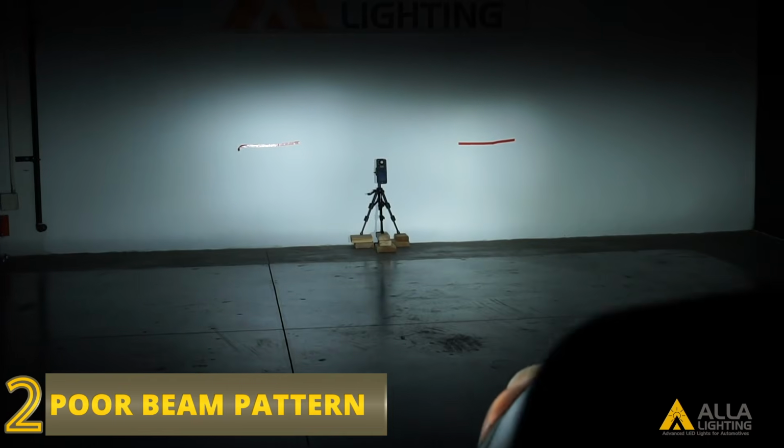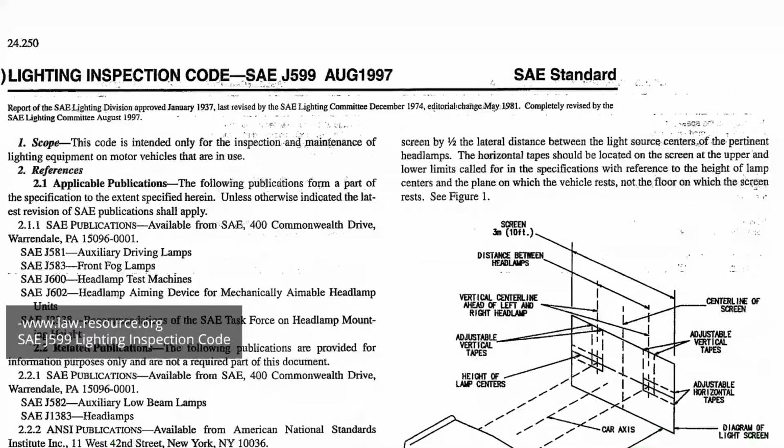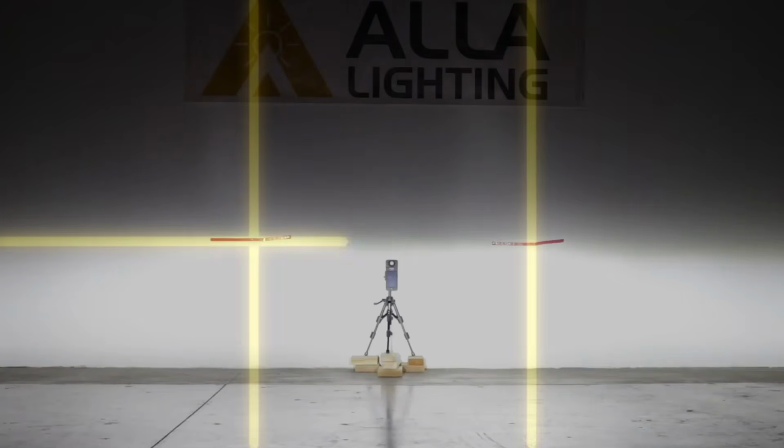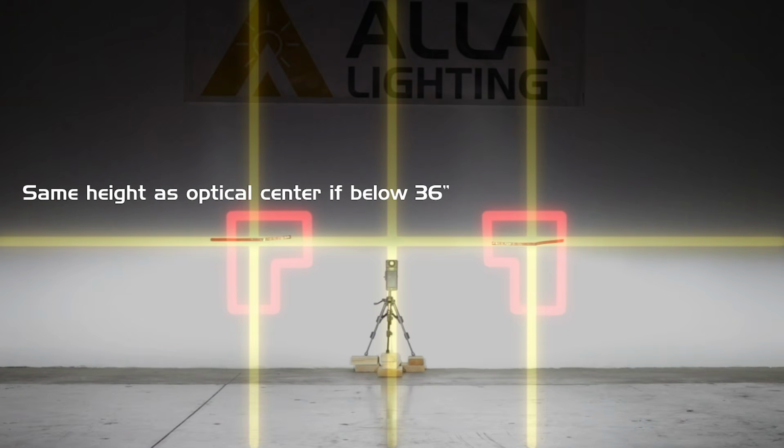2. Bad beam pattern. What is a bad beam pattern? SAE code J599-1997 regulates headlight beam patterns. In short, for most passenger cars, a clear beam pattern cast on the wall 25 feet in front at the same height of the vehicle's headlight optical center.